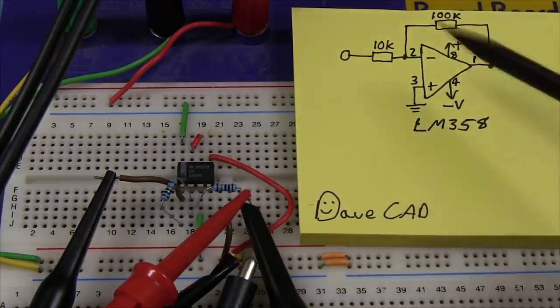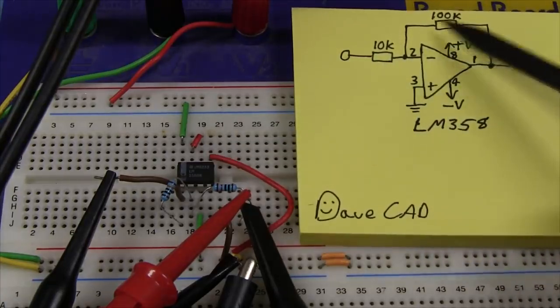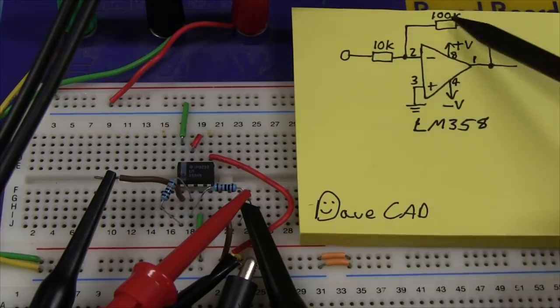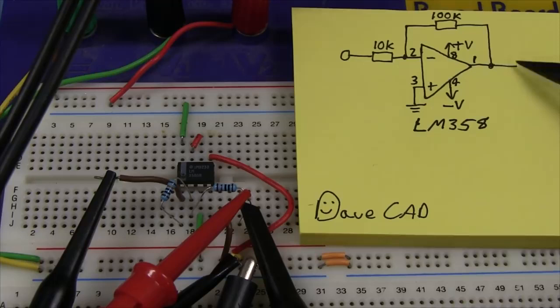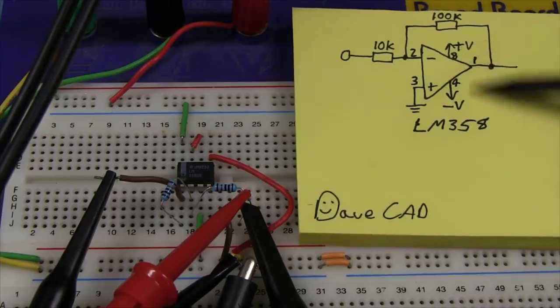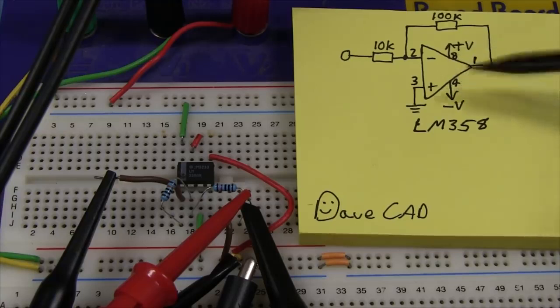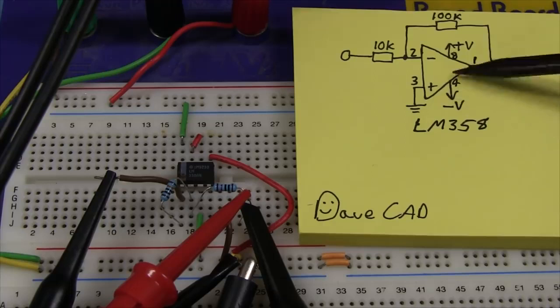Anyway, here we go. I've got it configured. I've got a 10K input resistor here, 100K feedback, so we've got a gain of 10. The formula, of course, is the feedback resistor on that one. Bingo, easy, times 10. So I'm going to feed 2 volts peak-to-peak input here. We should get 20 volts peak to peak on the output, so we're using pretty much near the maximum supply rail of the LM358. In this case, I'm powering it from plus minus 15 volts, so we have a split supply.